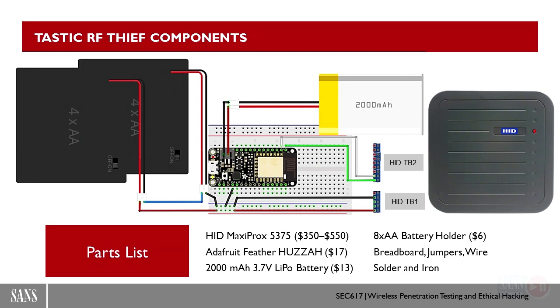The batteries that I have were free because I harvested them from laptop batteries that were being recycled, but we can still find them at reasonable prices, and they're reusable. That also said, the batteries are 3.7 volts as opposed to 1.5. We can use more of them to give more power to the reader, up to 22 volts. The more power we are providing to the reader means more power output and longer read ranges.